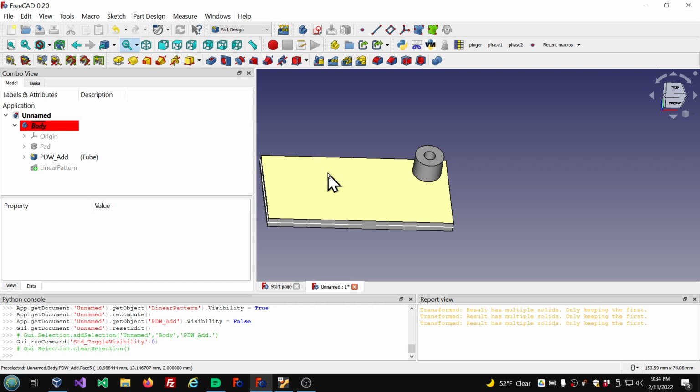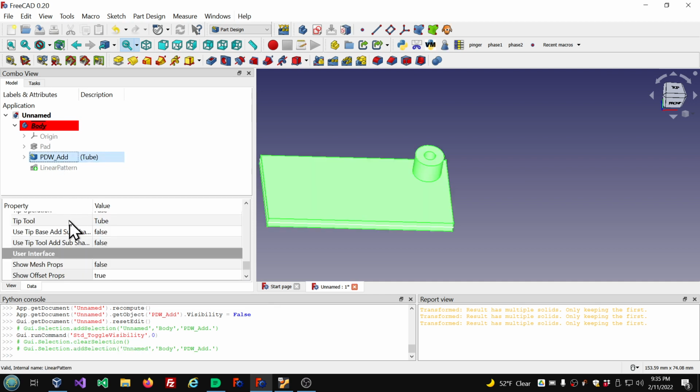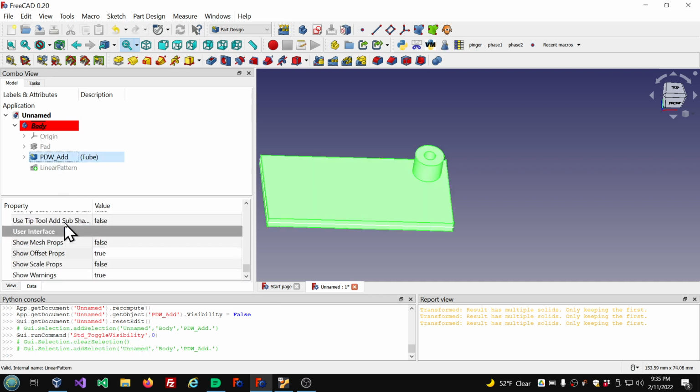So we have this thing that I call the solid feature chain in a body, and that includes all the solid features in the body. They're either fused to the previous feature or cut from the previous feature, which is the base feature property of each object. So each of these objects has a base feature property.